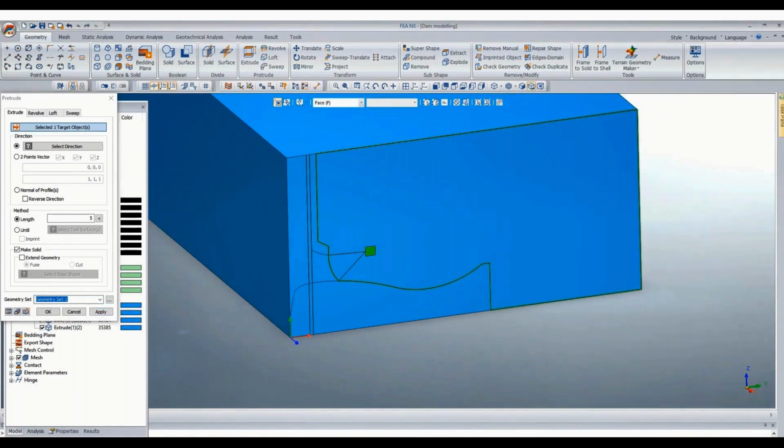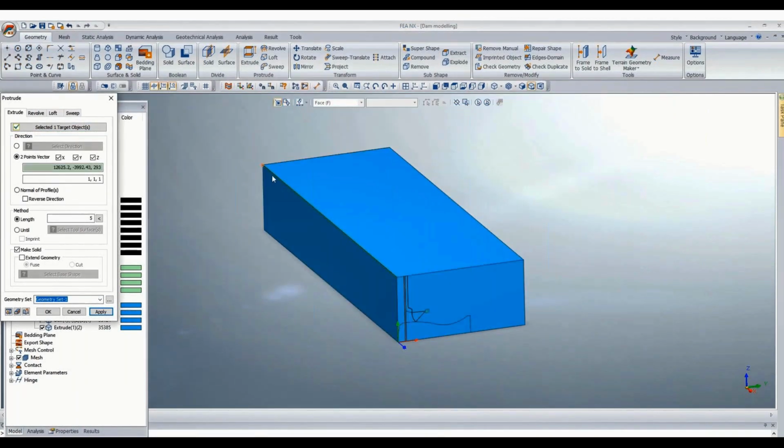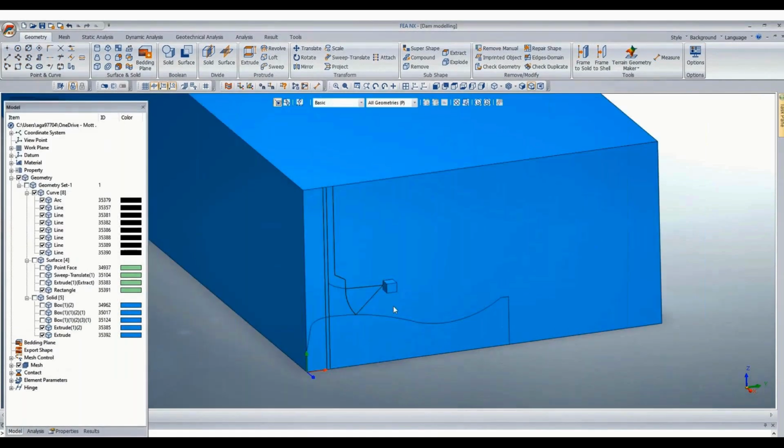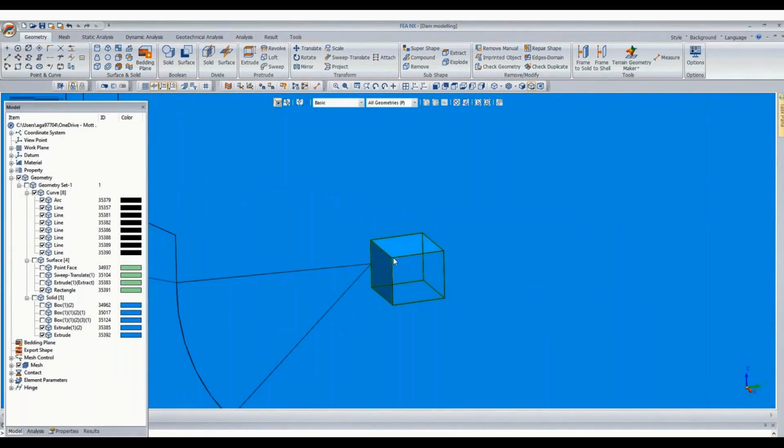How much was the... okay, arbitrarily I'll extrude this time. Later on extrude it again, say 5 meters. Okay, let's keep 5 meter. Okay, and from here I'll cut it at about 75 degrees.